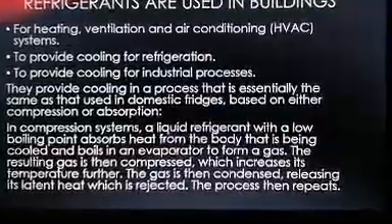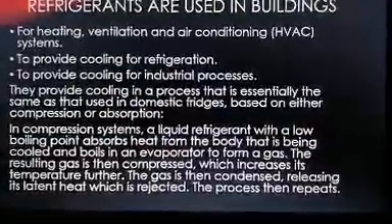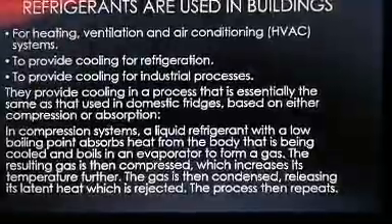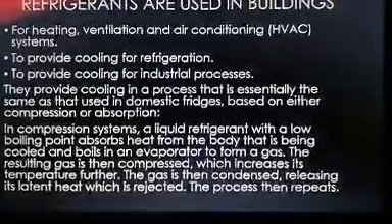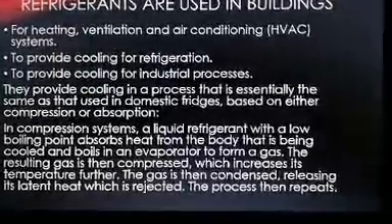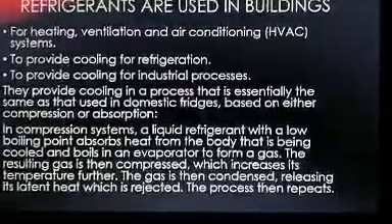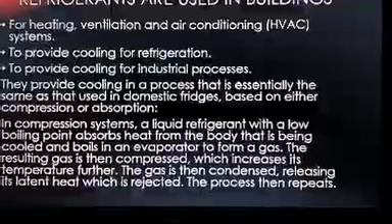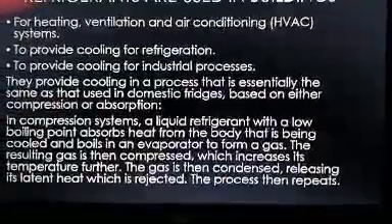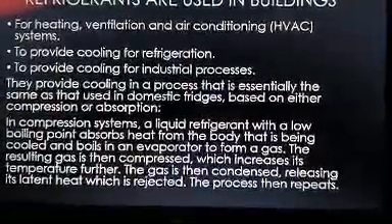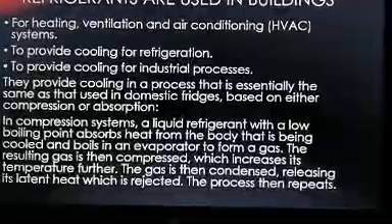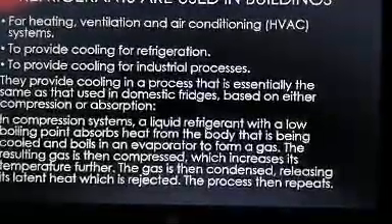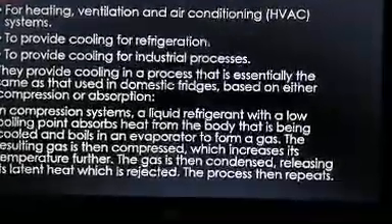In a compression system, a liquid refrigerant with a low boiling point absorbs heat from the body that is being cooled and boils in an evaporator to form a gas. The resulting gas is then compressed, which increases its temperature further. The gas is then condensed, releasing its latent heat, which is rejected. The process then repeats.